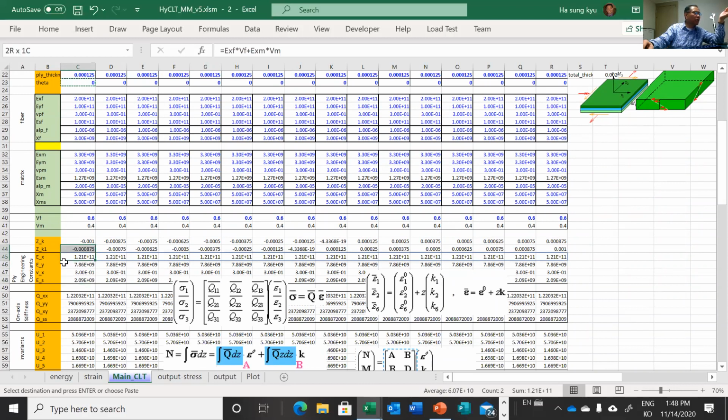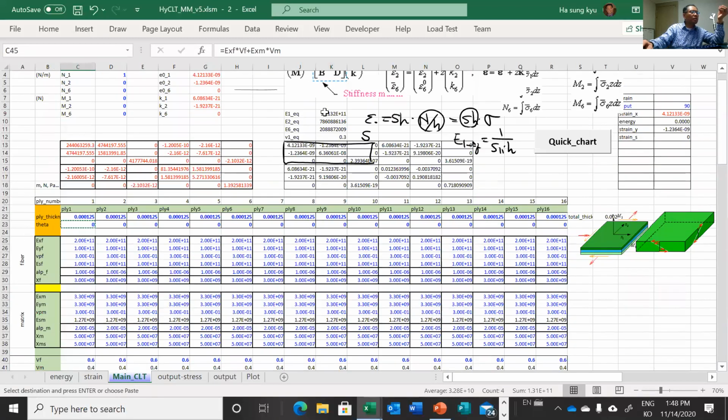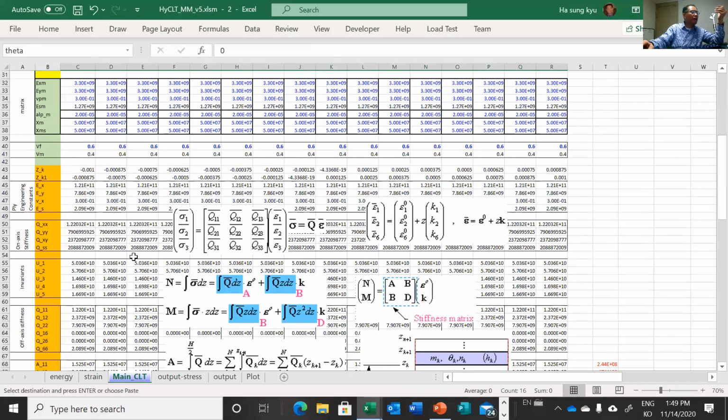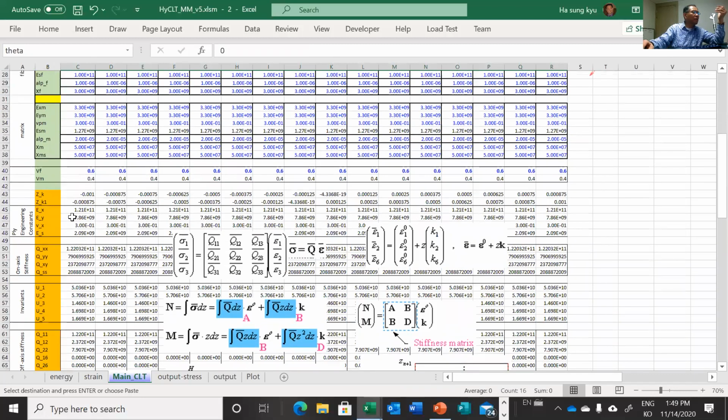That's the material we layered, right? This is the ply property, and that should be the same as the equivalent ply stiffness. Even though we have 16 plies, all plies have the same material property along their own axis.